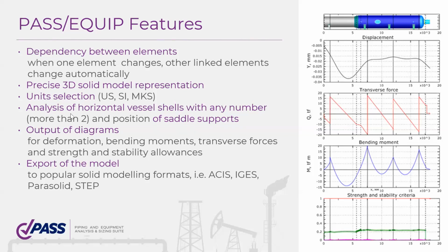And the interesting thing is that we can do some configurations which are statically undefined. For example, we can calculate vessels on more than 2 supports. You know, if we model it as a beam, it will be a statically undefined problem. So the software calculates, and the software represents all results in very easy to understand diagrams. So you can see all moments, forces, displacements along the vessel.